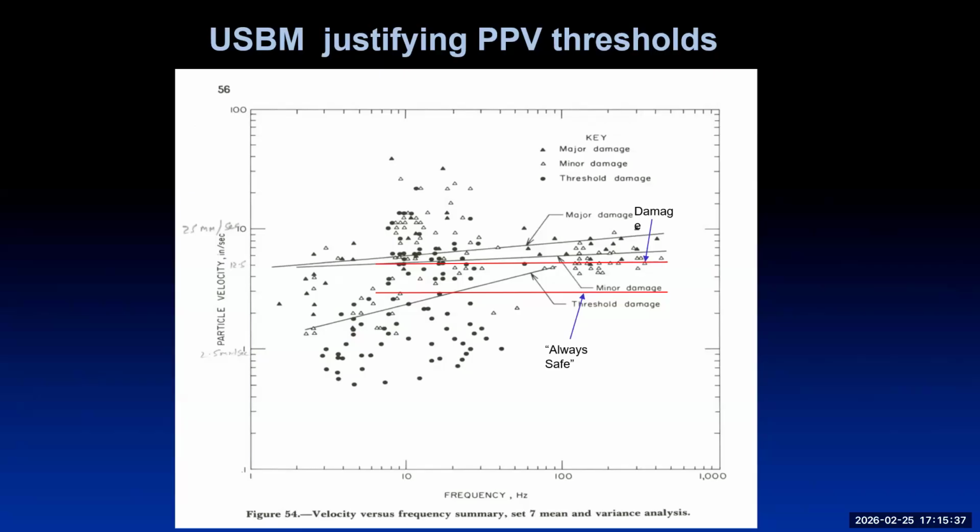Thank you, Doctor. But yeah, it's really important to realize that the methodology from 1980, around when Alan was doing his work and disseminating it around the globe, they were duplicating it for this study, all for the intent of avoiding damage and understanding how structures respond. They used the same techniques that our company uses and that are in the international standard ISO 4866. And it's very specific about measuring the response of a structure and very detailed about the accuracy necessary, what standards to use, and what methodology to use.